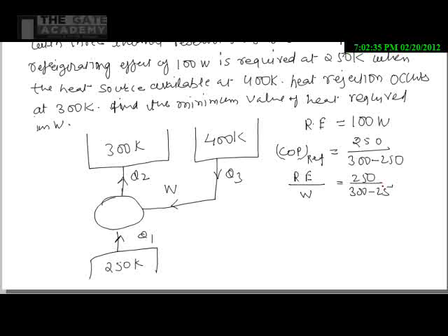So work done will be the refrigerating effect, that is 100 into 50 divided by 250. So work done will come 20 watt. By this way we can get the value of work done.